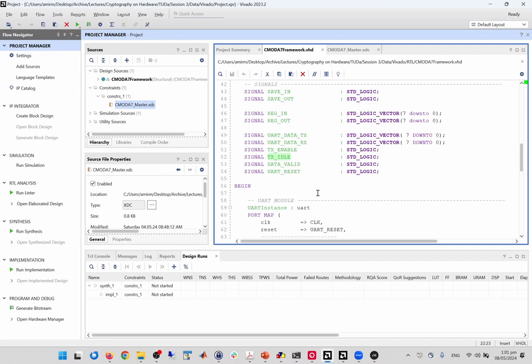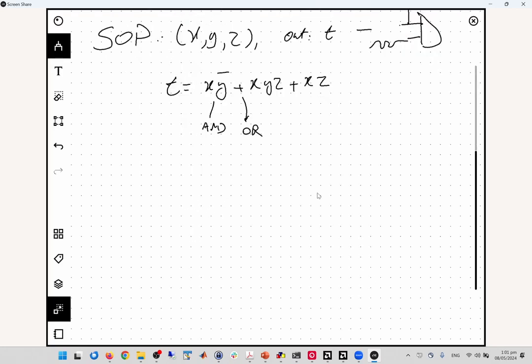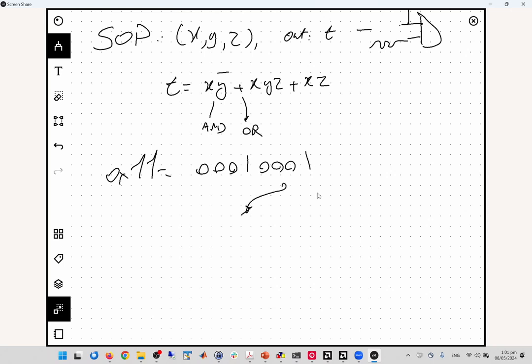And then the order of the bits will be different. For example, you send hex 1 1, which means 0, 0, 0, 1, 0, 0, 0, 1. Then it changes the order of the bits. It will be 1, 0, 0, 0, and 1, 0, 0, 0. Then it gives you actually 0x88. This is just this, nothing else.